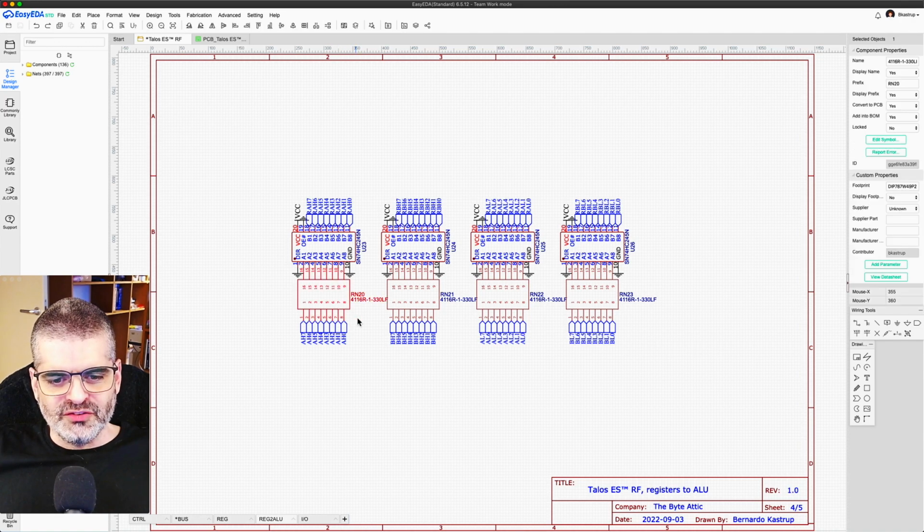You can think of these resistors as forming a low-pass RC filter together with the parasitic capacitance of the lines. And if you think of them this way, then it doesn't matter where you put them on the line. Wherever they are, they will absorb the higher harmonics and absorb the reflections anyway. So the difference is whether you're thinking in terms of avoiding the reflection or whether you're thinking in terms of absorbing the reflections that will happen. In my experience, it doesn't matter much. Even if you don't put these resistors close to the driver pins, they will still work because they work as low-pass RC filters.